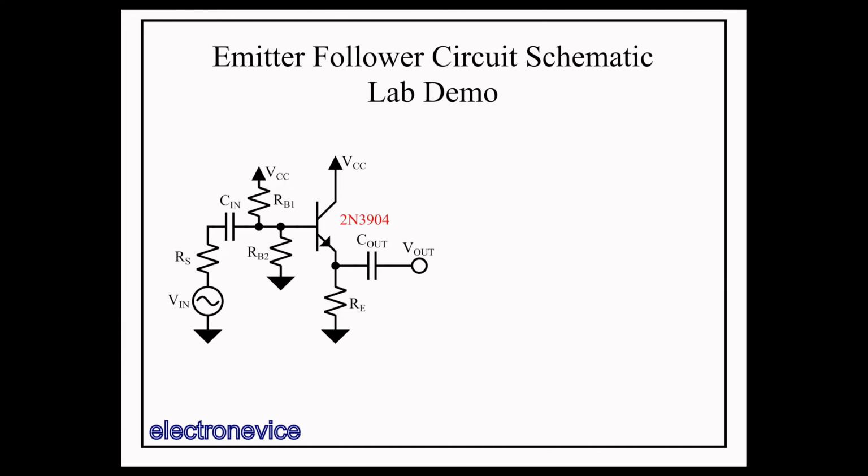As a result, if you look at datasheets such as TI's 12-bit ADC128S102, you'll see things like the ADC will deliver best performance when driven by a low impedance source. For the ADC128S102, it says less than 100 ohms for the source. For Microchip's 24-bit MCP3564R, it recommends tens of ohms for the source. So we're trying to get some pretty low resistances on the output here. Let's assume a value of 50 ohms for our desired maximum output impedance.